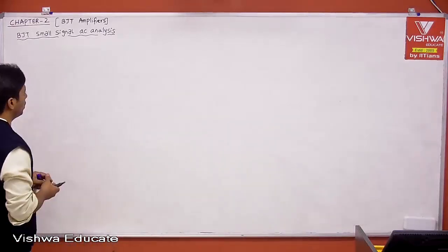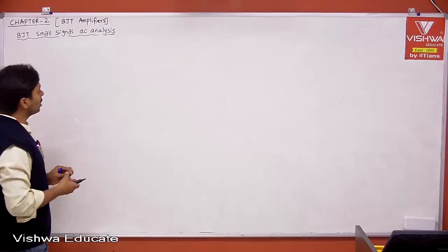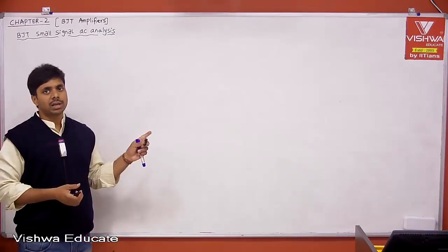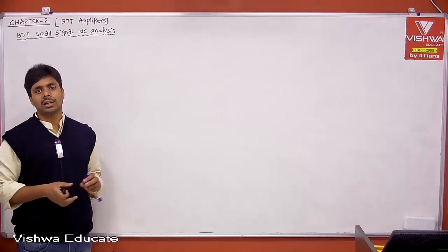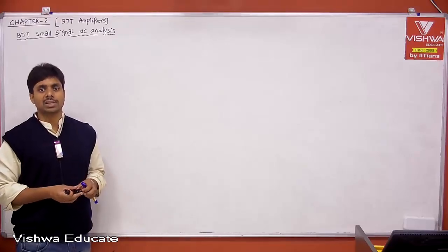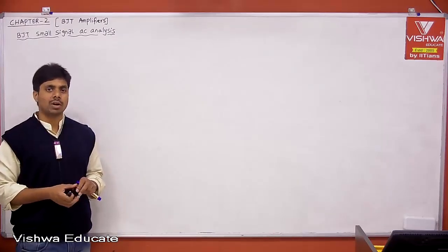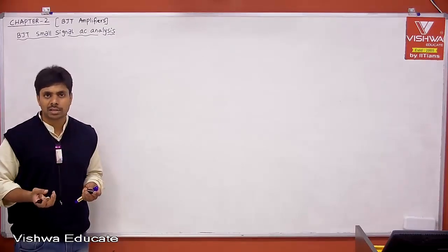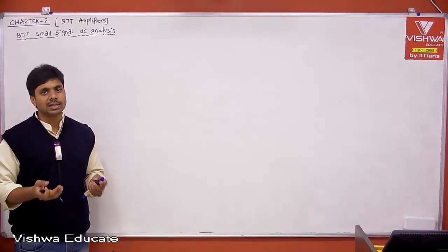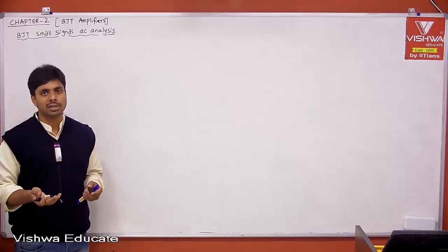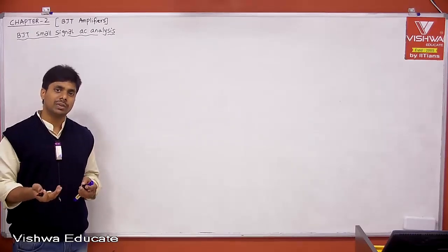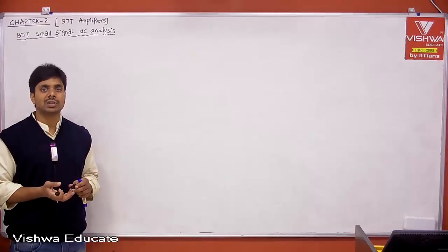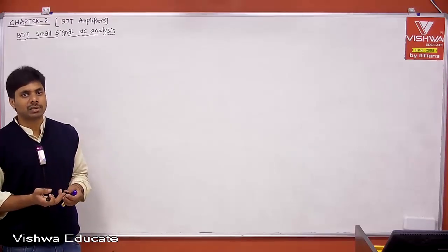Now, in the last session, I told you that when you take switch action or amplifier action, it is only a steady state equation or DC equation, where timing information is not there. But if I incorporate timing information, that is nothing but AC analysis, right? Let's see, at a given frequency, which is not zero frequency and not infinity frequency, how the equivalent circuit will change, which is basically a dynamic circuit, or dynamic resistance if it is a two-terminal device. Okay.